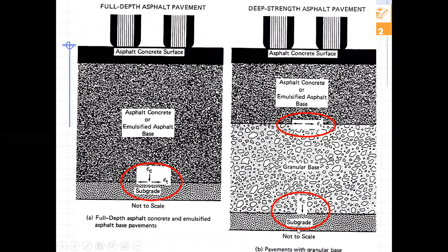So you see this other one that is called EZ. That's the compressive or vertical strain, and that one will produce a permanent deformation. We're going to talk about that one in a little while, maybe in 30 minutes from now. But what you refer to is a combination of this tensile strain and the compressive strain, both of them. Because this produces a deformation here, that translates here, that translates up here, and then you end up having both combined.